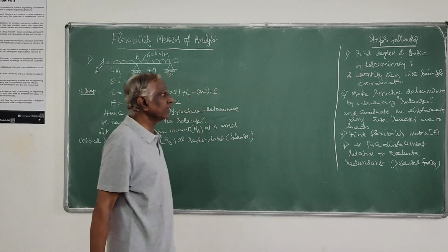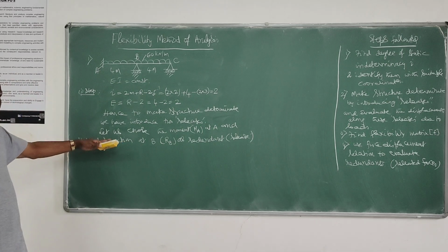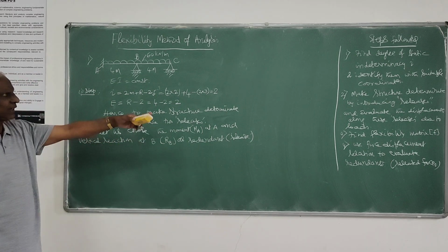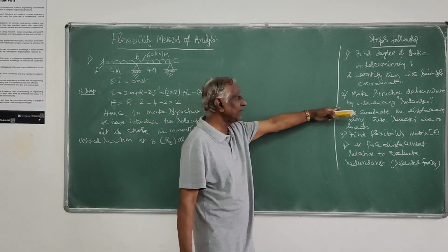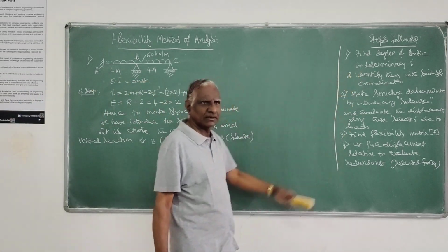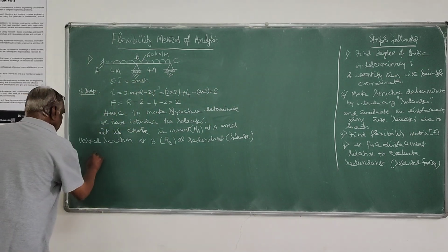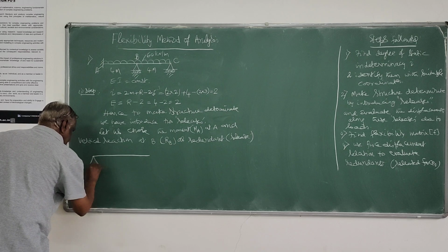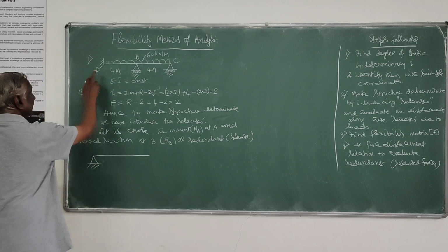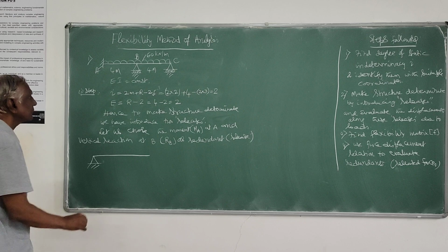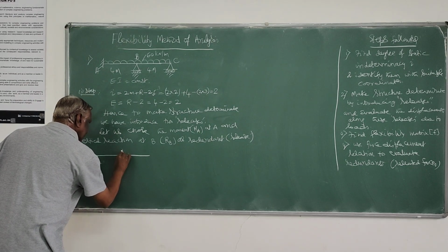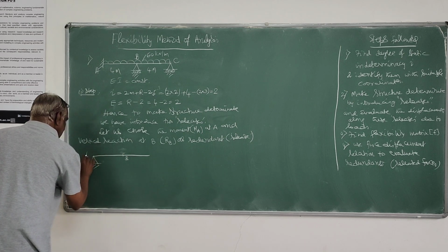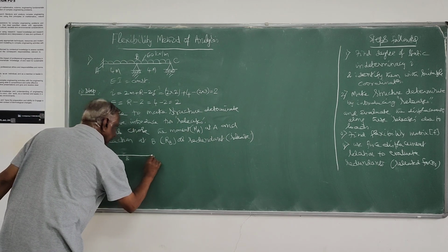Find the degree of static indeterminacy, then identify suitable coordinates, that is, whatever you have released in order to make it determinate. Of course, that comes in the second step that I have told you. And I have identified the coordinates. So the basic determinate structure now, since I have removed the moment at A, it becomes hinged. I have removed the reaction here at B, so that also comes like this, just free.